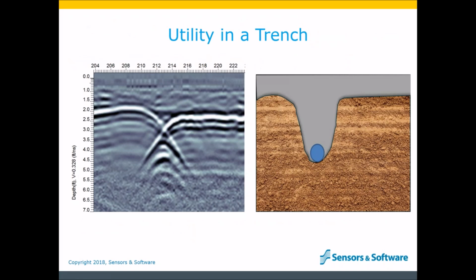Another tactic is to indirectly look for the evidence of the pipe, or what we call the effect of trenching. So remember that when a trench is dug and a pipe is dropped in, the trench is often backfilled with a different material, typically gravel. The evidence of trenching shows up as an X pattern, where the ground strata has been broken. The X pattern is the GPR picking up the walls of the trench, as seen below.